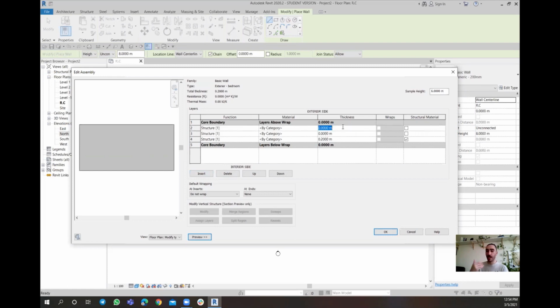So if I start to add some thicknesses, for example, for this one, I want to put, let's say, 0.2 meters, right? For the other one, I want to put it as 0.5. And for the last one, I want to modify that to, for example, 10. As you can see, all these layers would be customized right now. So the thicknesses are different.